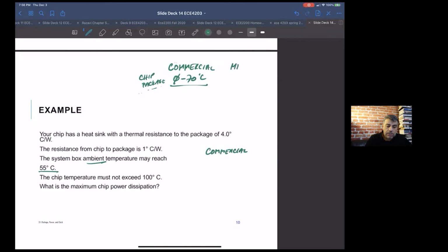Then you've got military, or industrial. I really don't know the numbers, it might be up to plus 85 degrees, and on the low end maybe minus 20, but it's wider. That means the chip you design for military or industrial needs tolerance to a wider range of temperatures, or higher temperatures, so it'll be more difficult to design. Usually the worst spec is automotive, which just scares everybody to death. I forgot what the high end is on automotive. That's the widest temperature spec, so toughest to design typically.